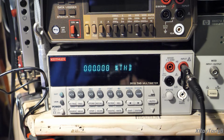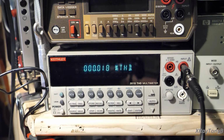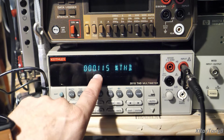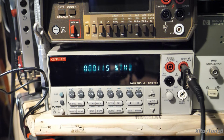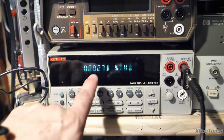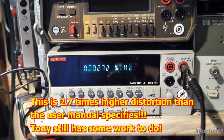So here we go. We're going to do our 14 watts per channel. And you can see right there, it's pretty good. I mean, look, 0.02% THD. And we're going to go up to about 60. And you can see it climbs up pretty substantially at 60 watts per channel. It's now 0.1%, which for this amp I think is high. And then we'll go to the 110 watts per channel, and you can see it goes even higher. Now 0.3% to me for this amplifier, I don't think is very good.